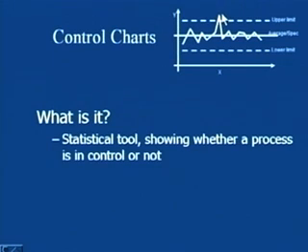Once we plot the data, if any point is going outside, then we check the records to see what happened to this product at the time of manufacturing. There may be some possibility that while manufacturing this particular product, the operator might have used the wrong die, might have used the wrong tool, might not have used the coolant. So, there may be some special reason.